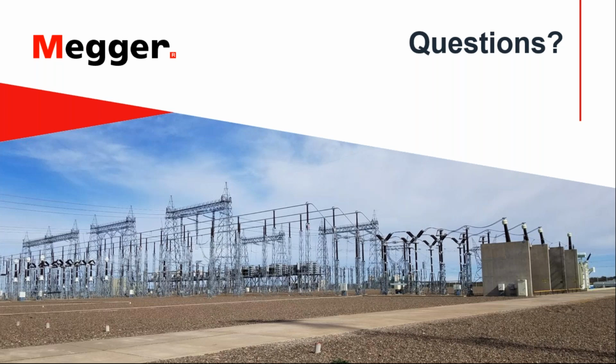Thank you, Michael. That's a great question. It's a little bit related to what Niklas answered, just a question before Volney. We need to understand that when we use the dynamic resistance technique to assess the quality of the arcing contacts, we are not comparing or measuring that length versus the main contact of the same pole.